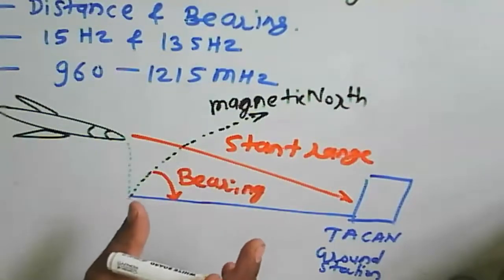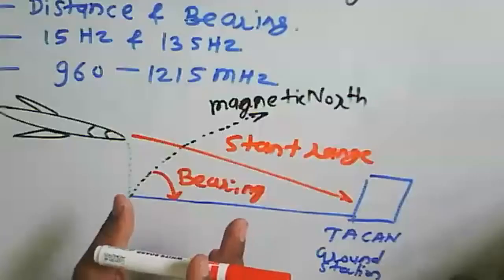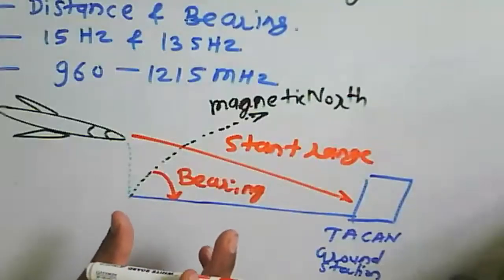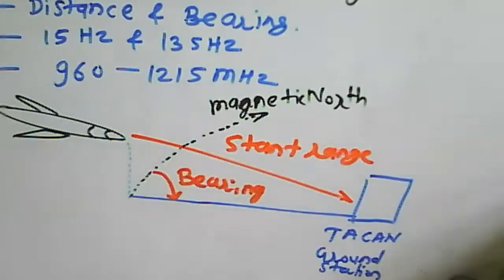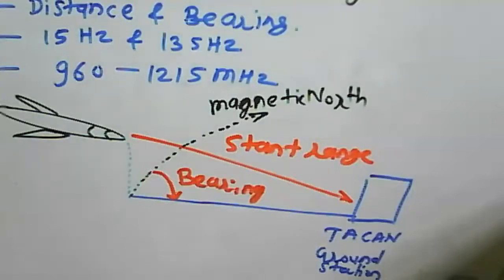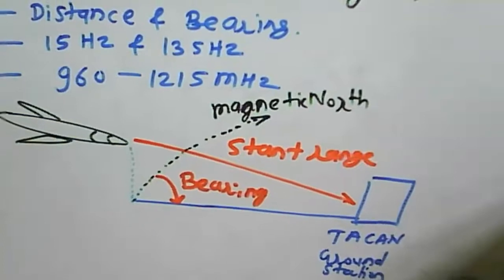Okay, generally you can say that this is called the flight phase, approximately the height in terms of feet. Just like a microwave landing system, the altitude and so on have to be updated. If there is no microwave landing system available there, then in that case a TACAN is useful to obtain the range as well as the bearing.